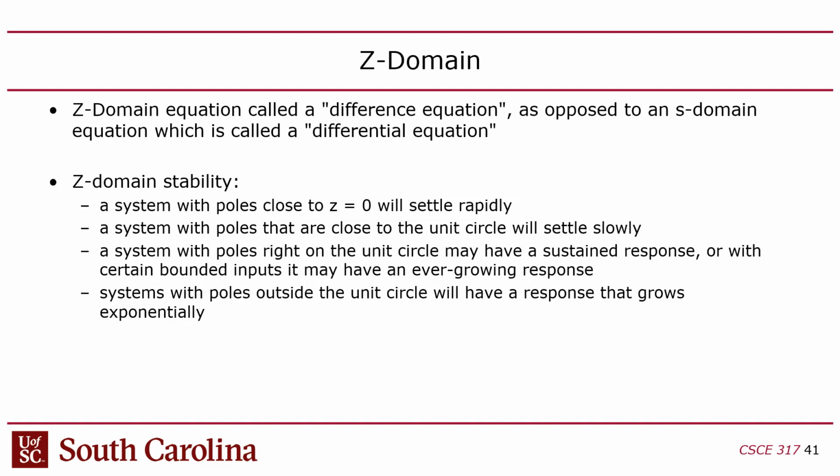You can convert the time domain to a Z domain through Laplace transform? No, I don't know, Z transform. They don't have a fancy French name for it. It's just called the Z transform. No one takes credit for the Z transform. They don't have a Laplace. Also, it's not called a differential equation anymore, the time domain. It's called a difference equation because a differential equation is only for continuous. Okay, so then you convert it to Z domain, and then you can calculate the transfer function in the Z domain. However, the stability test is completely screwed up in the Z domain.